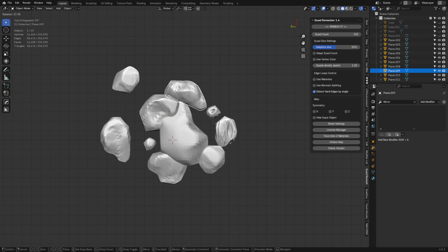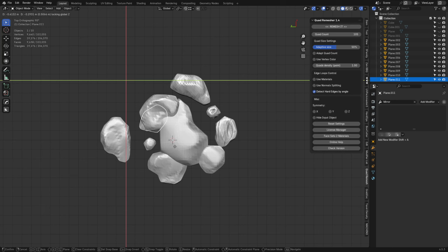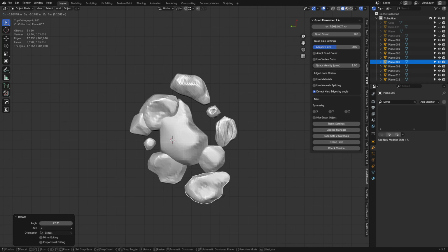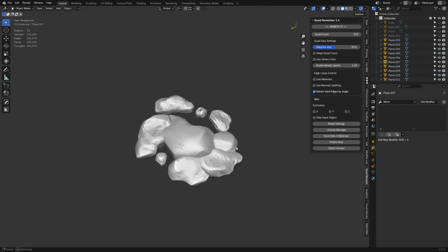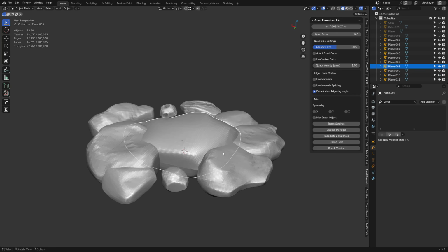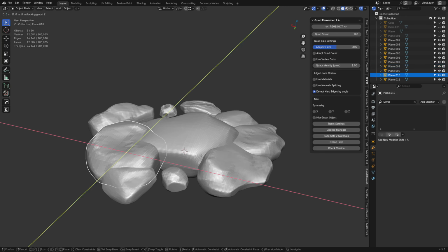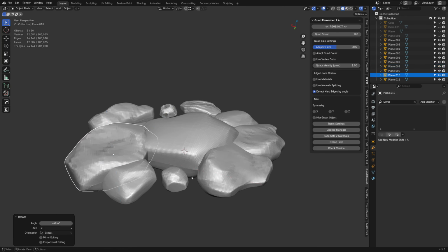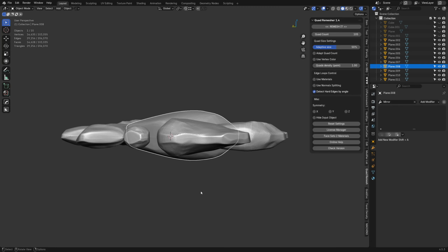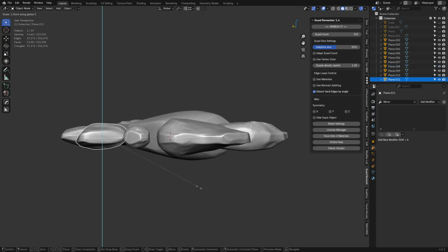This is where things kind of go crazy. You can do UV maps on all of these and have them textured, and then you can just bring them in here. The way you do it in Blender is a little bit rough, because you could combine them together and remesh them, and then project the UVs from the old models to the new one. But it doesn't always work out great, and a lot of times you're better off unwrapping them. But it's possible, so I just wanted to point that out. There are some really interesting things you can do, but you won't know about them necessarily.